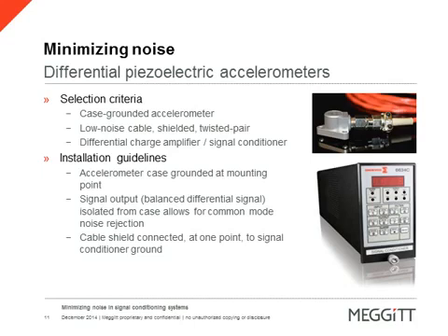Common mode rejection is accomplished with the sensor's plus and minus leads connected through the twisted, shielded, low noise cable and going into the amplifier. Once it reaches the amplifier, the common mode kicks in and the signals that are unwanted and common to each line are rejected.